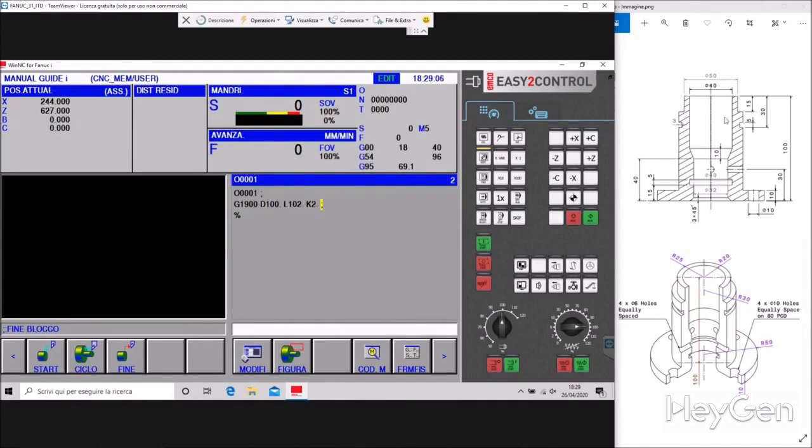First of all, we need to clear out this entire area, or possibly drill inside the piece. Let's say that I have always told you that the most difficult operations are those that need to be done first. In this case, I would drill first and then think about roughing. We have a 32 mm hole, so we use a 32 mm bit. Check the tool compensator table, essential for the process. A bit is on compensator 11. T11 bit radius is 3.